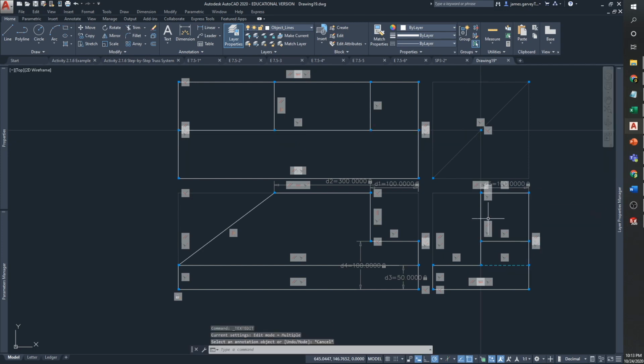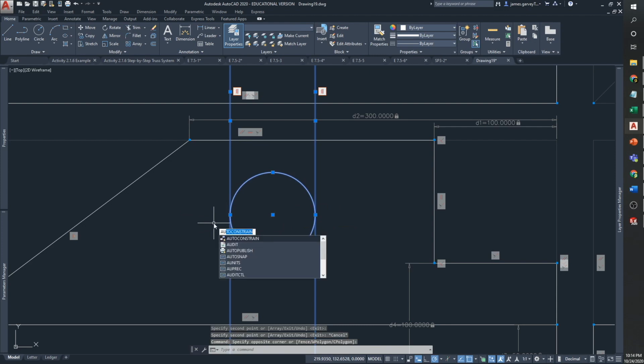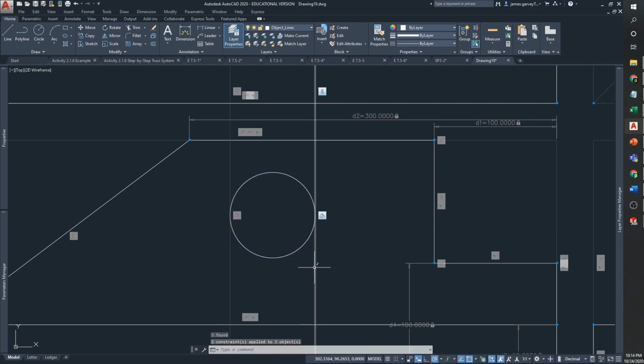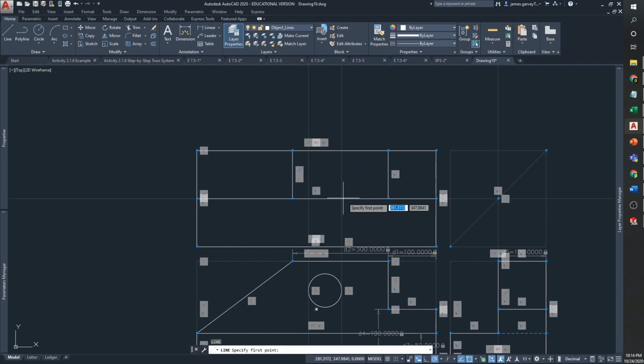Trying to think if there's anything, if say there was a hole in this part here, I've had the best luck once again using your construction lines here to keep things, your hidden lines on the other views, in line. So you can put points on these edges, or just getting that selected, do auto on that, and that should put tangent and I believe vertical on that. So those are good to go. Put our lines here.